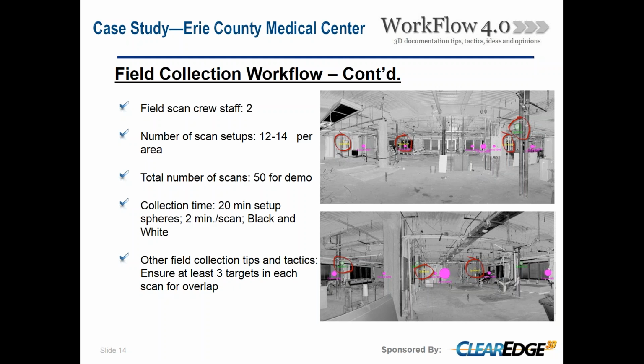One of the things we always tried to do was make sure at least 3 spheres are in the scan. This allowed us to quickly and accurately register them. I found even more than that is okay, so I typically do overkill. In the 2 scans on the right, you can see I've circled the spheres that have the same names and overlap.